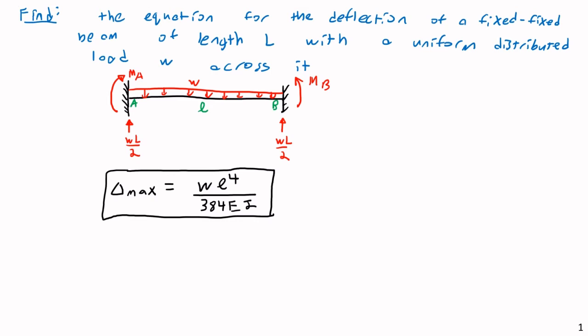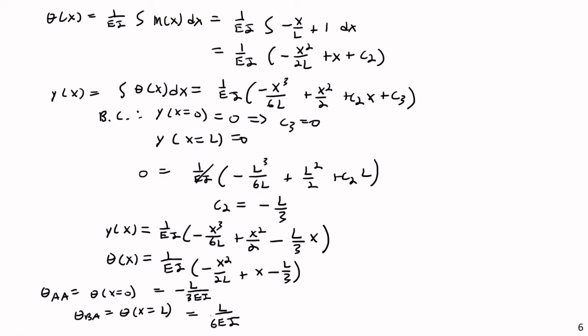If you remember from the force method, the theory of the force method, basically what we're saying is, let's say I remove these redundant forces, in this case the redundant moments at the start of the beam. If I remove this moment here and here, how much is this thing going to bend? And then I want to find how much moment it takes to bend that thing back up to put it back where it was. I'm going to do that by finding how much a unit load or a unit moment here causes it to bend. And then I'm going to apply a balance of rotations, a mathematical balance of rotations, to find that value.